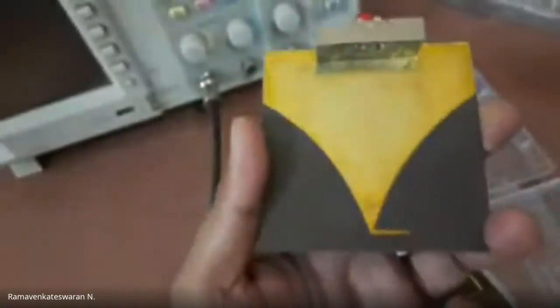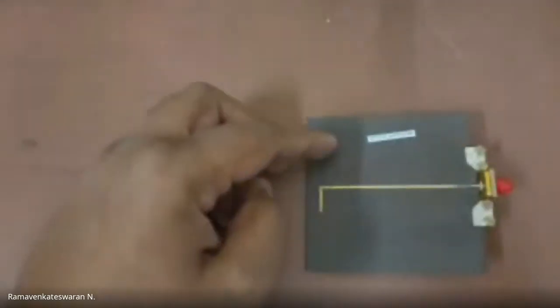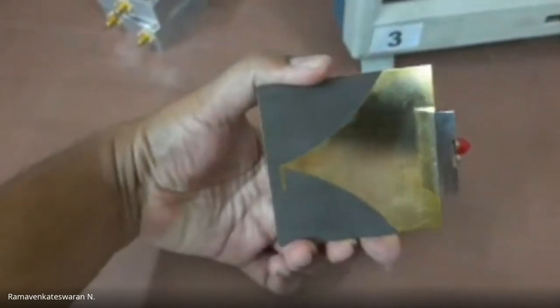So you can see the antenna which is printed onto this dielectric substrate. And peculiarly, you can see the structure in the bottom. So this is a top dipole, and in the bottom there is another one. This is a small dipole, and this is a small dipole. If you take it reverse, it is just the opposite print. So effectively, you have one more on the bottom side, another antenna.